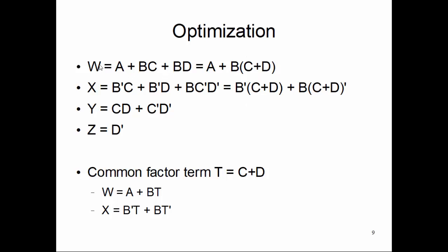Because K-map focuses on one single Boolean function, either optimizing W or optimizing X or optimizing Y. That means if there is scope to reuse some of the intermediate logic that is already done for another output variable, the K-map technique cannot predict that absolutely.